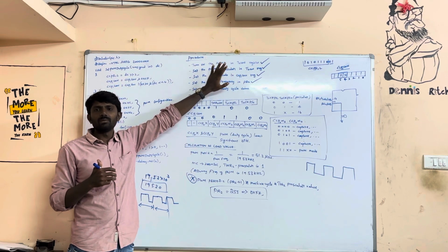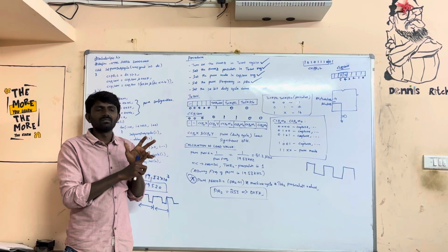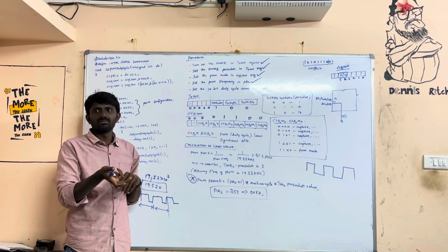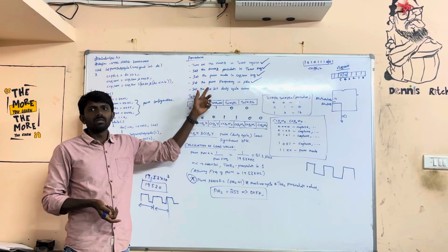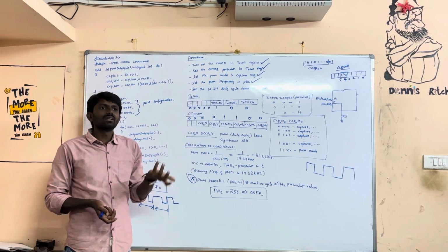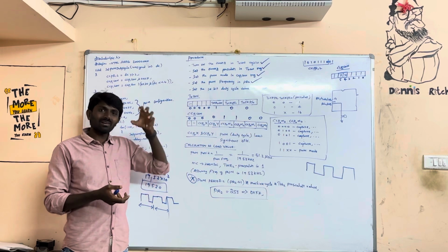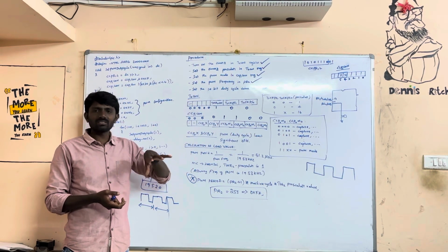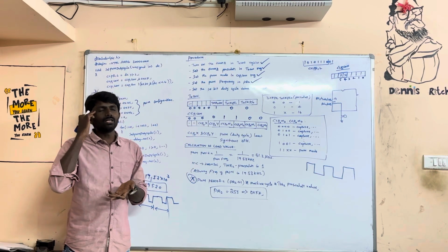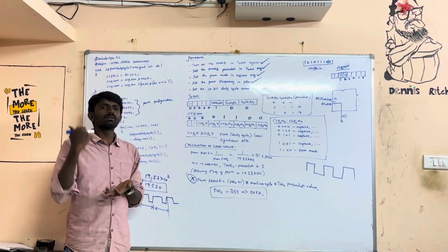If I am using PWM, I need to enable Timer 2, set the Timer 2 prescaler, and then enable PWM mode. Then you set the frequency, and finally you set the 10-bit duty cycle value. Got it, right? That overall concept you need to remember. Nobody expects which register. If you are able to remember, that is well and good, but don't force yourself.